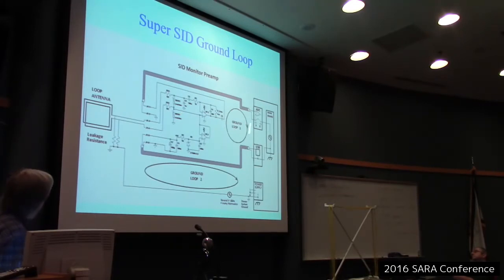One of the things that's a possibility, and I need to look at it some more, maybe work with Tom on it, is that if you want to use USB power, you could put a common mode filter in here, rather than a ferrite choke on the outside of the cable. You actually want to break the USB cable, because it's only used for power, and put a common mode choke here. That has a good potential for breaking that loop there. So you get rid of one of the places where ground noise gets in.